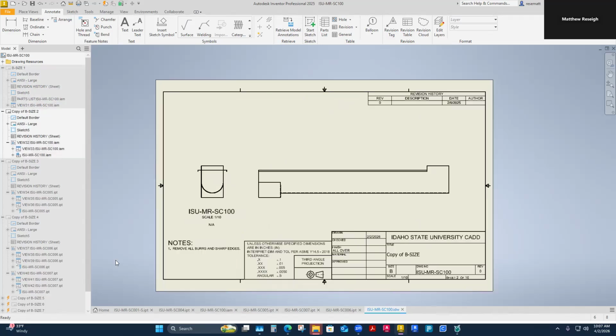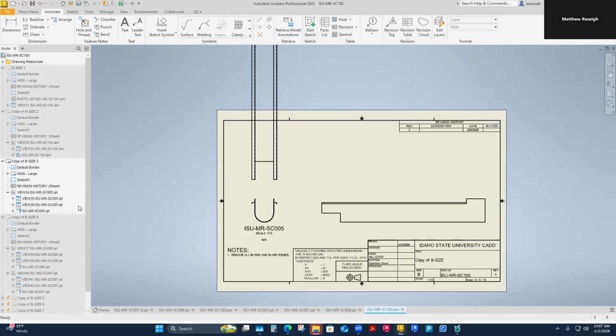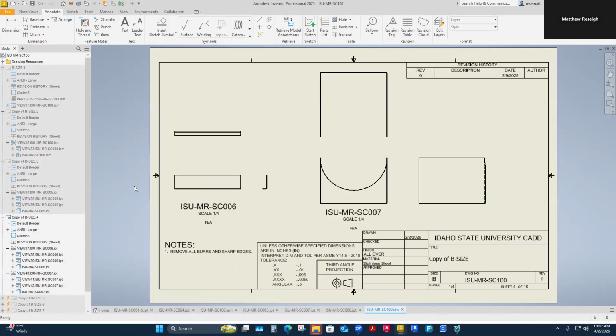And then I come into here and I say housing assembly. And then I would come into this one and say this sheet is housing parts, sheet one, or housing parts. So I might have two sheets of housing parts. That's the way I'm systematically breaking down how to detail this out on sheets: think of an overall assembly, then a sub-assembly, and then the parts associated with the sub-assembly.